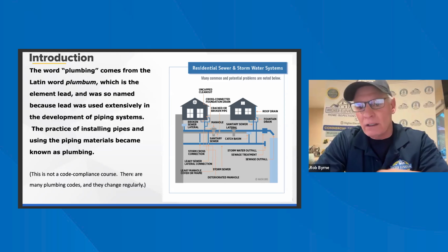Okay, now we're going to look at our kitchen plumbing. Just like bathrooms, we want to check all our faucets, make sure that hot is hot, cold is cold. So first thing I do is I put it on hot. We want to check both sides. We're going to open our cabinet, let it get hot. Down here, now dishwashers are not part of the standards of practice, but because there's plumbing, we typically look at them. Understand you are exceeding the standards.